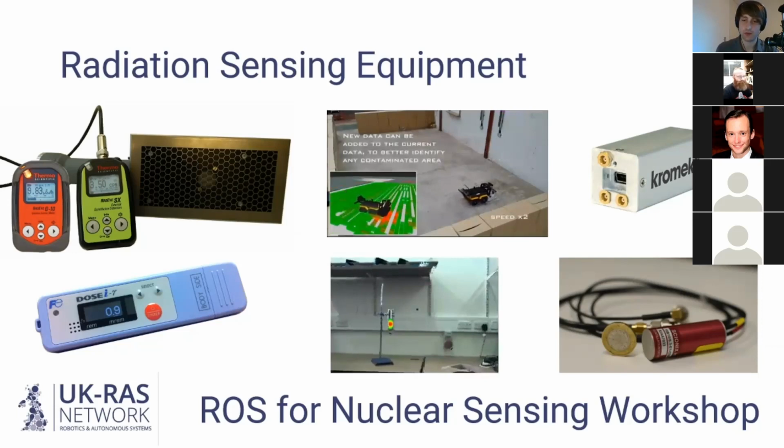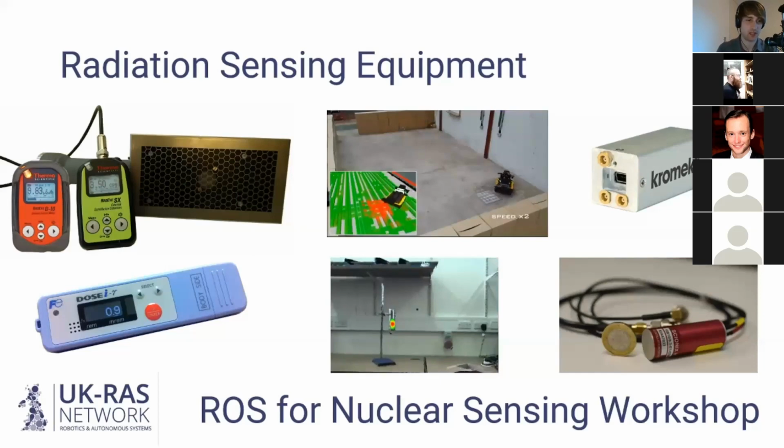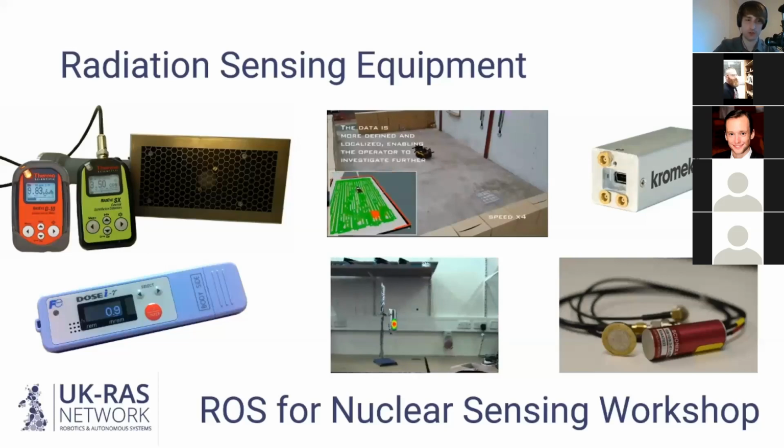Now, in the bottom left, these were the first robots that went into Fukushima after the tsunami and everything. They didn't necessarily have the luxury of these integrated radiation sensors, and neither did they really have the time. So they took these electronic personal dosimeters, this little blue stick, which were just used by the staff, and just strapped them to the robots. So these are solid state detectors, and all they did is point a camera down at the screen and then just read that back.